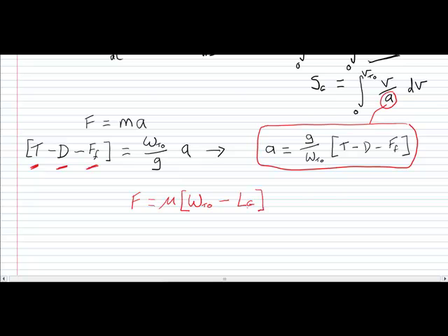So actually the reaction force provided by the ground will be decreasing, so the rolling resistance will be decreasing as the aircraft accelerates down the runway. And again, so this is F, and we can take this relationship here and put it into this equation here. And again, this should really be accounted for in your performance modelling.